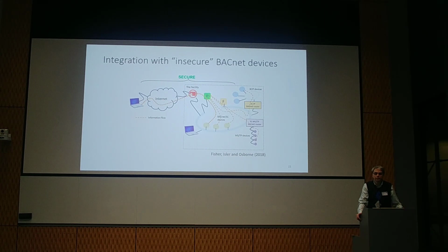Hey Jim, your three little round devices on the bottom of the ring, they have the red data path, which is secure, and they have the little black path, which is not. Do they have to have the black path, or can they just live on the red one? The black path is sort of a physical connection. Got it. And the dashed orange lines are a logical connection to the primary hub. Right. Yeah, they have both of them. But philosophically, can you actually get to that secure device without being a registered device yourself? Or is that one safe because it only talks secure anyway? You can't get to it. Those devices only talk BACnet SC.